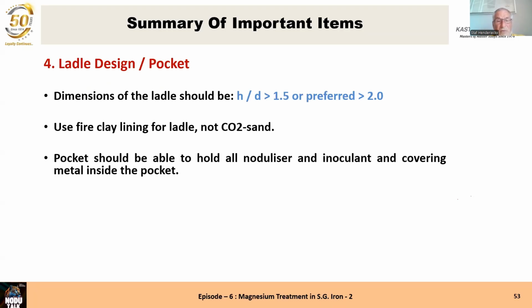And the pocket in your ladle should be able to hold all the nodulizer and inoculant and cover it inside the pocket, so that this material is not a bump above the pocket.